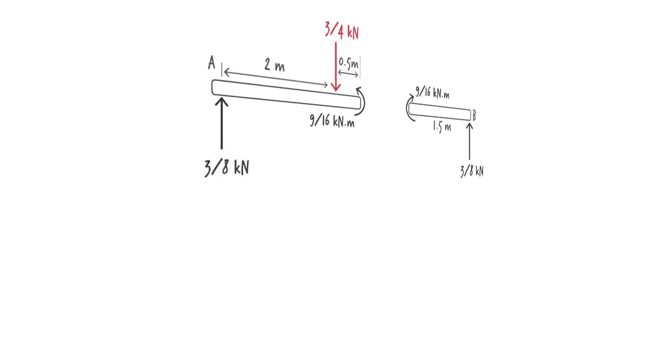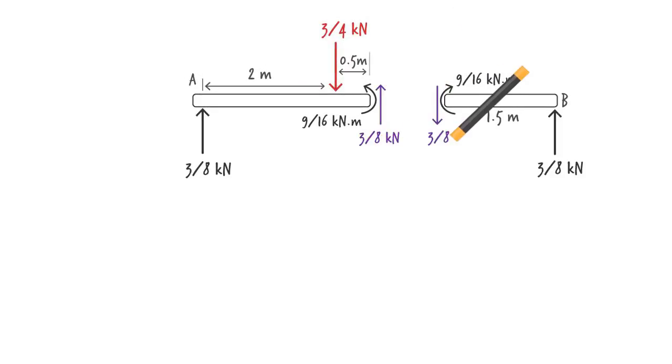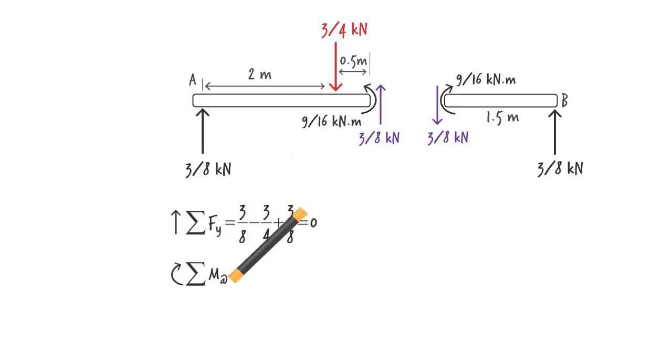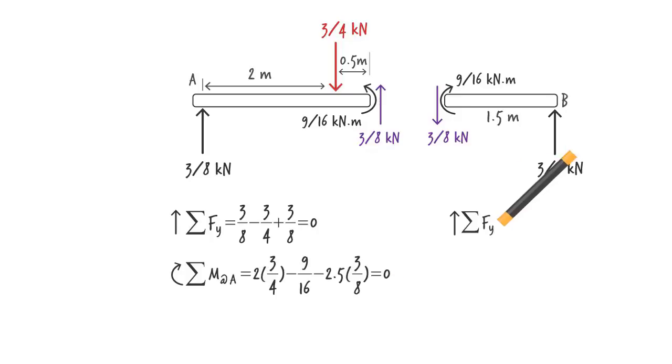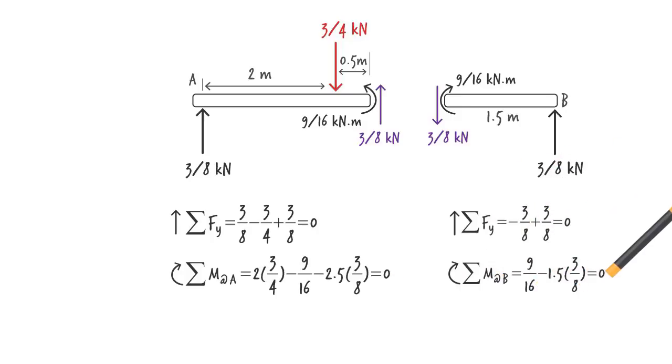So at point D, the internal forces in the beam are. Note how these forces ensure that both the left and the right segments of the beam remain in static equilibrium. The sum of the forces in the y direction and the sum of the moments in both free body diagrams equal 0. This makes calculating shear and moment in beams rather straightforward. We don't need to figure out the internal tension and compression forces in the beam in order to determine shear and moment. We can determine these forces directly from the static equilibrium equations.